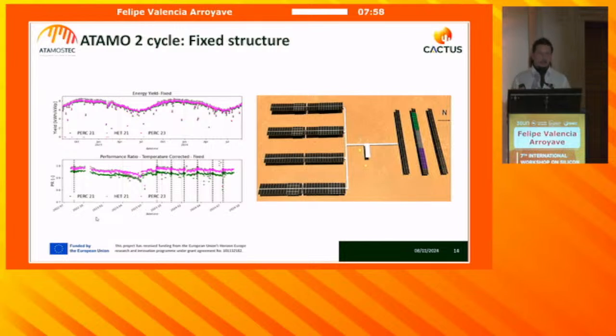But we did an experiment to see how sensitive the heterojunction is to the soiling, and we didn't clean the plant for about 6 months. And you can see how the performance ratio started to go down, until the performance ratio goes from the top to the bottom of all technologies.